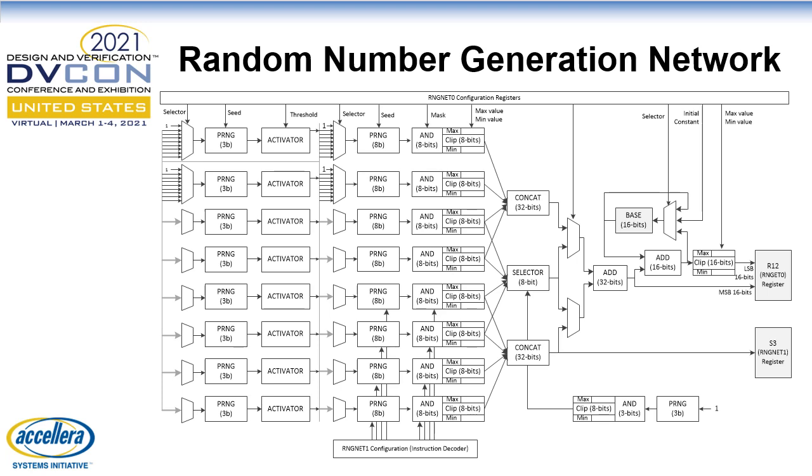It is possible to write a function that generates random LUT values at runtime. This is a general way and still possible in TISC. As a better solution, TISC provides a random number generation network, shortly called RNGNet for more simplicity. RNGNet is a generalized network mainly targeted for LUT generation. The author had investigated all of the random LUT generation functions currently used in multimedia IP testbenches and devised a generalized architecture that can cover the majority of them with acceptable hardware area.